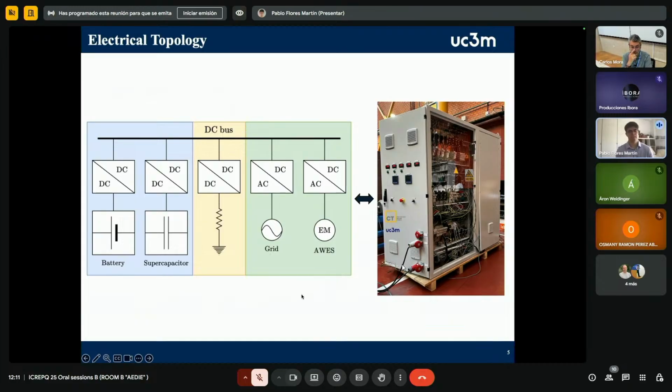The battery operates in high voltage side control, meaning that the DC boost voltage must be maintained at all times between 1 per unit and 1.06 per unit. If it goes above that limit, the battery absorbs power. If it falls below that limit, it delivers power. If it stays between, it stays idle. On the other hand, the supercapacitor operates in low voltage side control with a current limitation, allowing it to adjust its power absorption or delivery continuously.